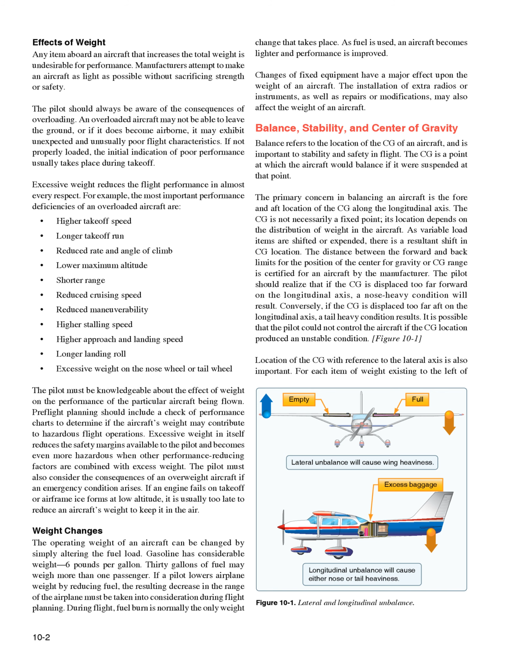During flight, fuel burn is normally the only weight change that takes place. As fuel is used, an aircraft becomes lighter and performance is improved. Changes of fixed equipment have a major effect upon the weight of an aircraft. The installation of extra radios or instruments, as well as repairs or modifications, may also affect the weight of an aircraft.